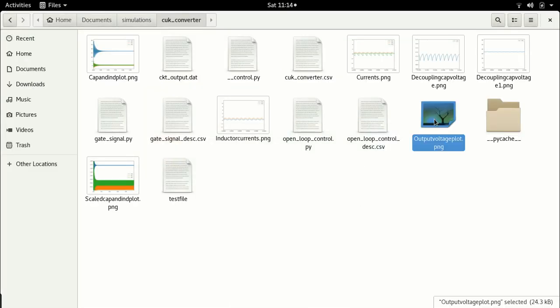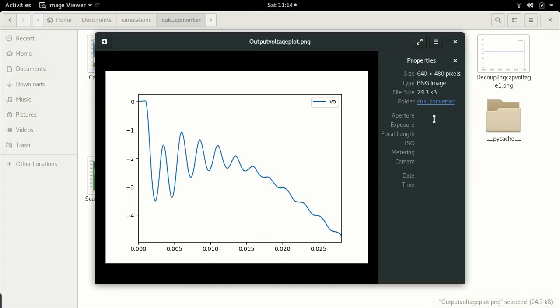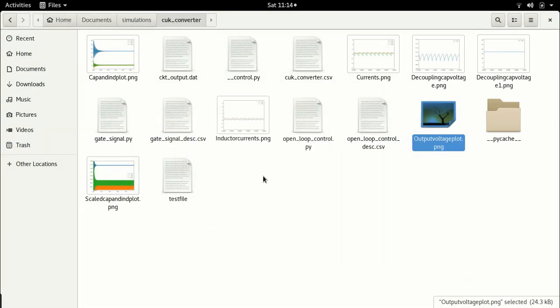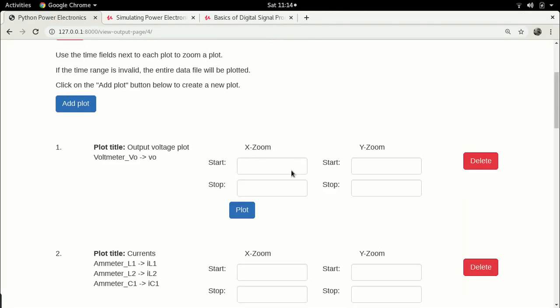And this is the output voltage. So this is only expected. Remember, the voltage is always negative because a Cuk converter produces a negative voltage. And you see the voltage starts at 0 initially as we are increasing the modulation signal, and now you see it is gradually increasing. Of course, we can plot it again and we'll see the increase even further.